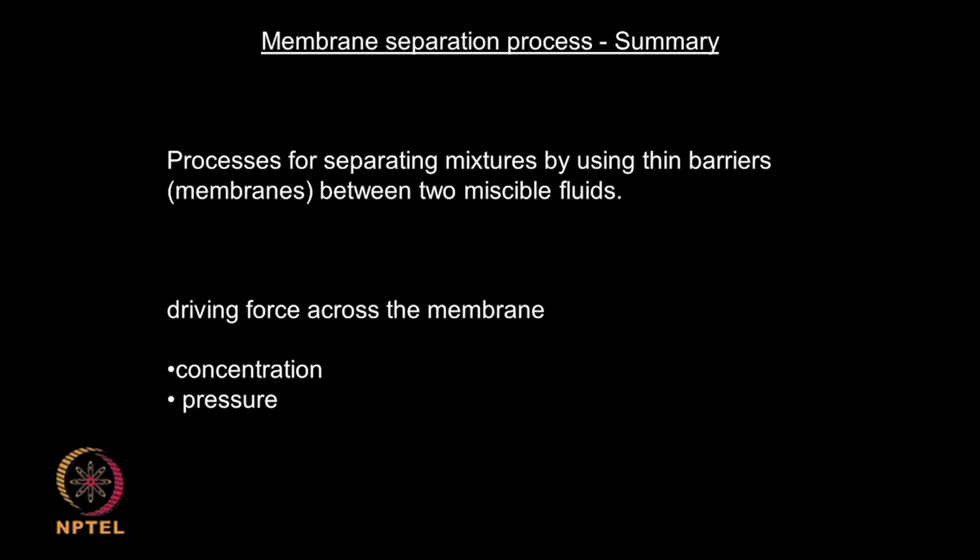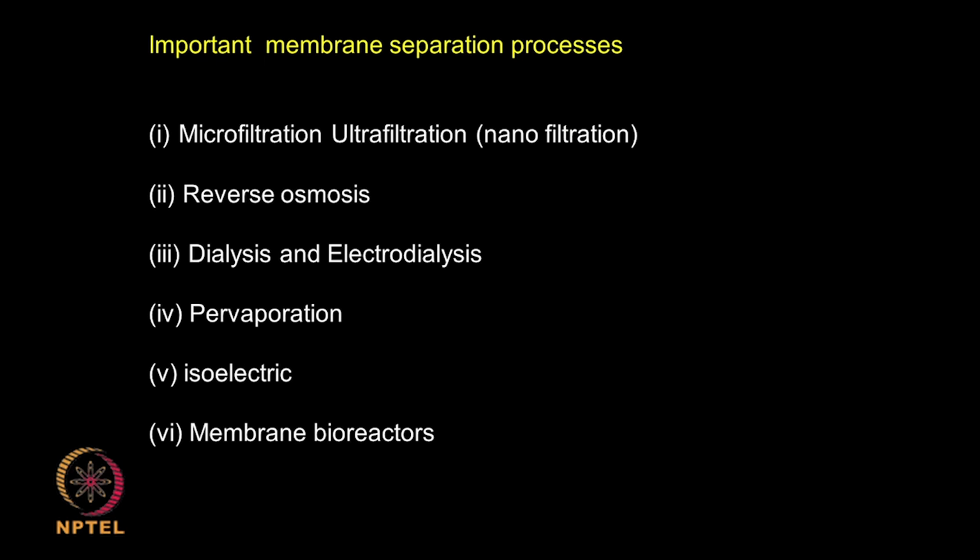So, we have spent a couple of lectures on membrane systems. Membranes are a process for separating mixtures by using thin barriers, polymeric, synthetic or non synthetic material, between two immiscible fluids. The driving force, although I have said concentration and pressure, can also be voltage and so on. We looked at a large number of systems: microfiltration, ultrafiltration, nanofiltration, reverse osmosis, dialysis, which is very important in the medical field, electrodialysis, pervaporation, isoelectric focusing, and membrane bioreactors. So, there is a large number of applications for membranes and it is growing day by day.